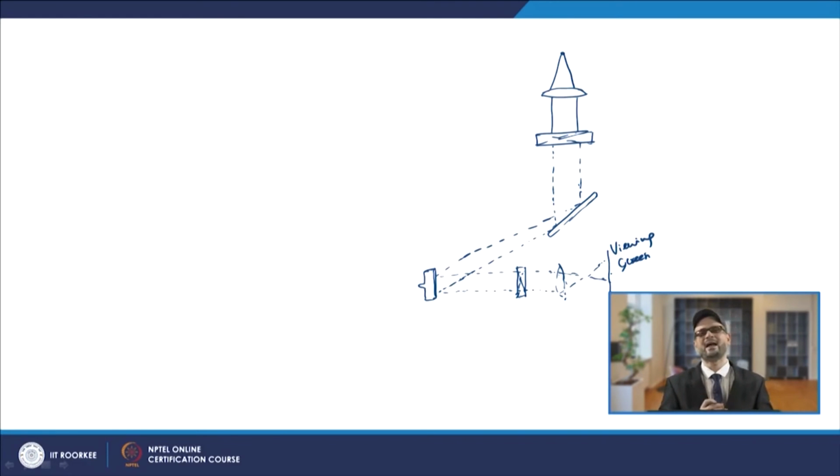So you can have the location, and you can have the sign and magnitude of that maximum strain, measured by looking at the fringes on that viewing screen. So this is the photo stress method, which is used for calculating residual stress values.